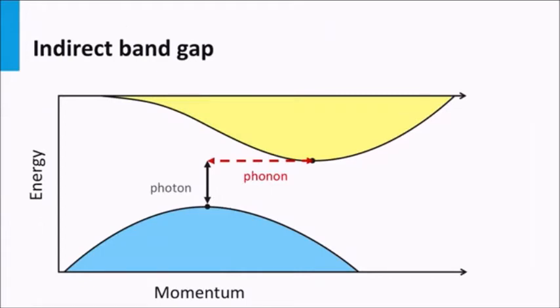An important consequence of a disordered lattice is that the electron momentum is poorly defined, in contrast to crystalline silicon. In crystalline silicon, the electronic band diagram versus lattice momentum looks like this. Both energy and momentum transfer are needed to excite an electron from the valence band to the conduction band. Crystalline silicon is an indirect bandgap material.